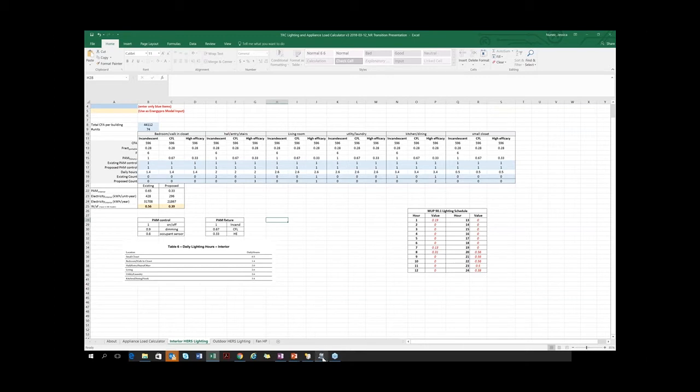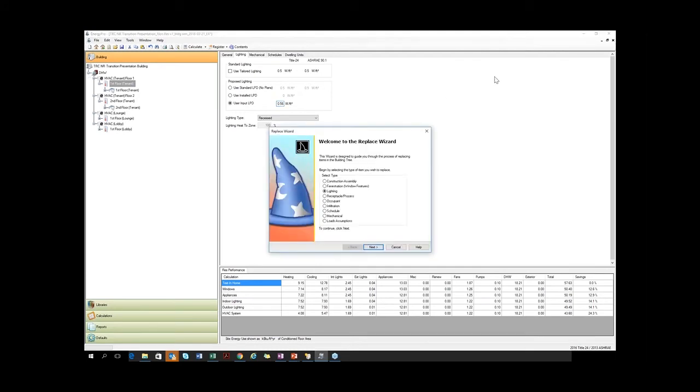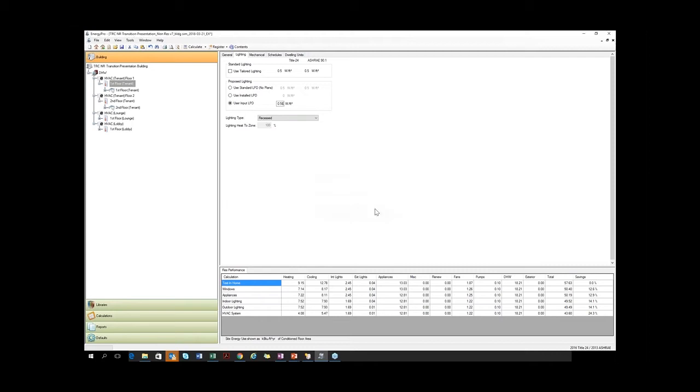And the way you input these values into the model is you have this watts per square foot, existing and proposed. So you have to do a 2-model approach now. You can't just do the alternatives tab. So in the first model, you'll put the existing. So we'll come in here. And where this goes is you could come in here if you have one zone and put the value here. But since we have multiple zones, we want to replace them all at once. And we could change the ones that are 0 to 0.56. And now we see that all of those have that value. Any questions on this?